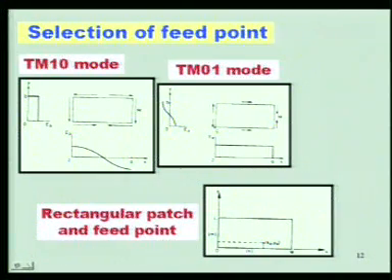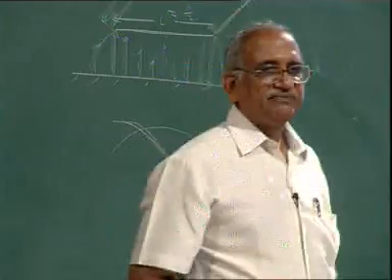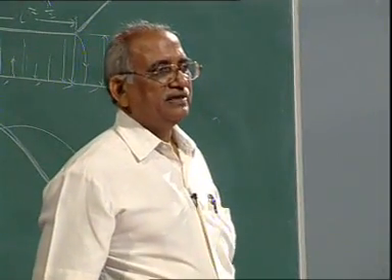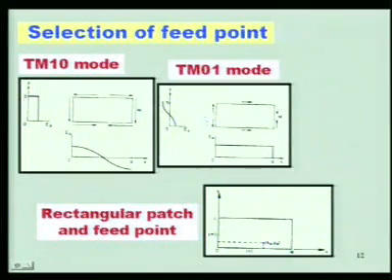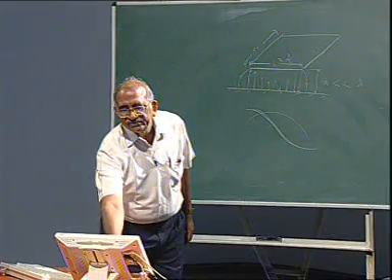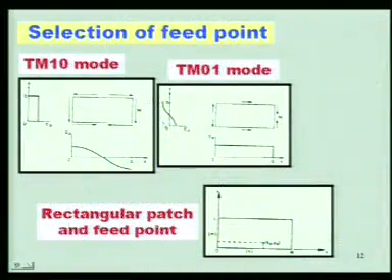So, naturally, the resonant frequency corresponding to this mode will be higher, because the corresponding dimension is smaller. Okay. Something like lambda will be equal to twice w. If this is the width of the line, then the corresponding lambda will be twice of w, and lambda corresponding to this will be twice the length.